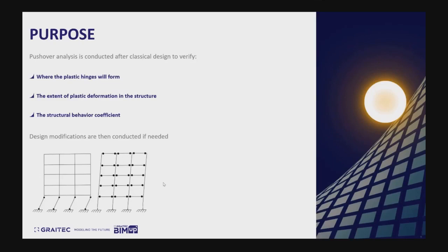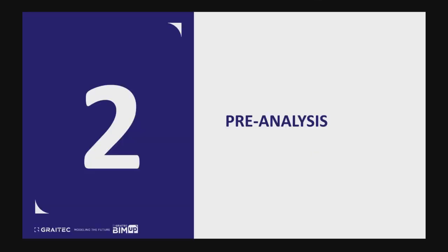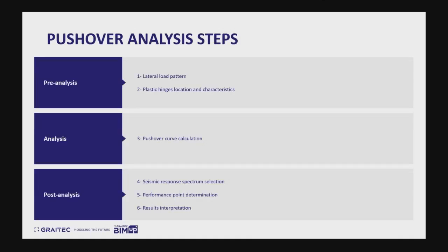Next, we will see how to use pushover analysis in advanced design. Three major steps are required to conduct a proper pushover analysis. First, we have the pre-analysis, where input is made on the model. Then we have the analysis, where calculations are made. And finally, we have the post-analysis, in which results interpretation is carried out. Now let's focus on the pre-analysis input phase.